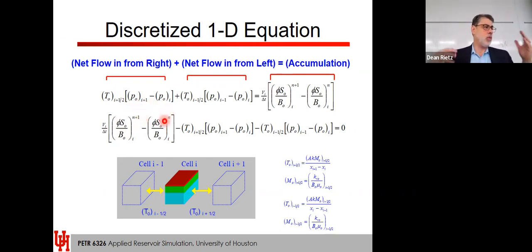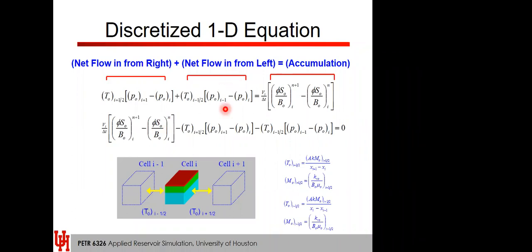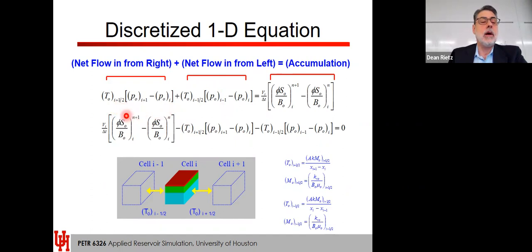Okay, so remember there's one value of pressure, and that is a value that's assigned to the grid block. Now we're saying, what's the transmissibility and then delta P? Basically, Darcy's law. We're really calculating the flow going from this one to this one when you have a delta pressure. If you have strong delta pressure, there's a lot of flow, but it also depends on the transmissibility.